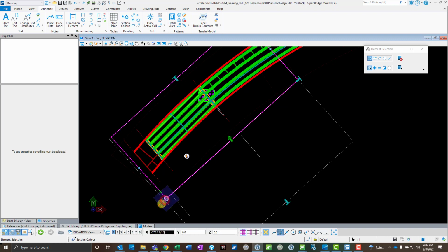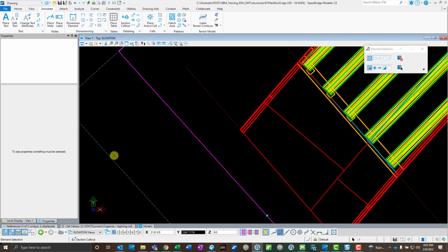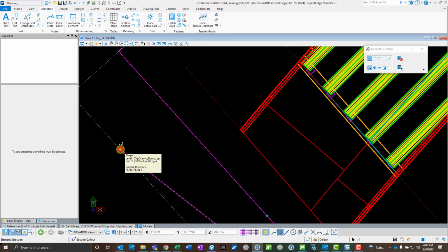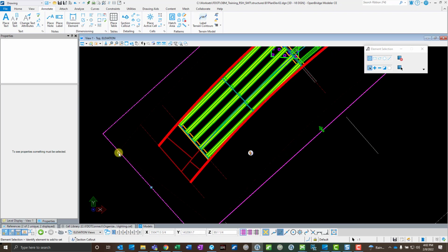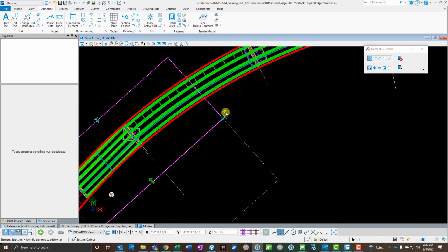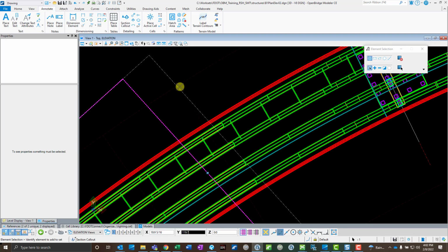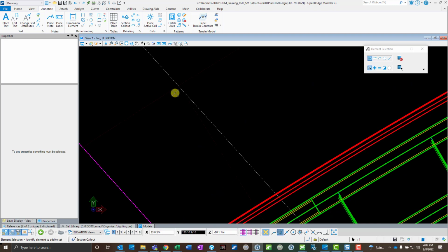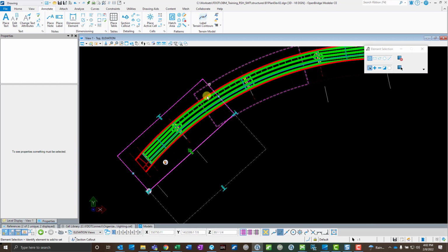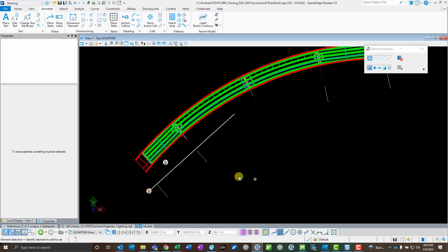section callout tool, grab the handle, and let's pull it out and get it to whatever the controlling point is in terms of how the bridge is curved. So in my case, it's going to be up here. I'm going to snap it out to the beginning left point of that boundary, and then same thing over here. I'm going to grab that pink handle and extend it to that point right here. It's kind of hard to see because that transparency is on there, but it's right there. So now that's going to be matching up my plan view with my elevation view much better.